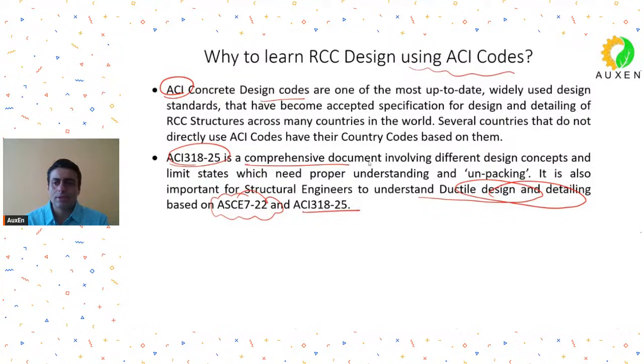Which is the IS 13920 in the Indian context. But here, the ductile design and detailing, as well as the normal RCC design, is covered in the ACI 318, and for the load calculations, for whichever load you want to do the calculations for, the document is ASCE 7-22.